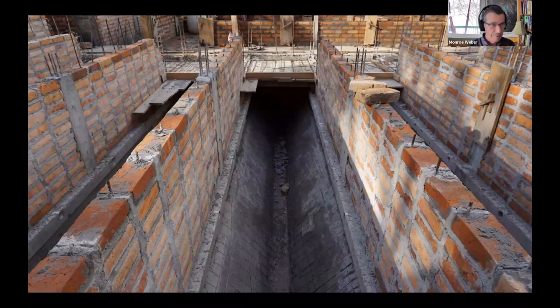And the reason is that these are load-bearing walls that have to be waterproof and have to resist significant hydrostatic pressure, because you have to be able to drain one tank while the others are still online. And that means there's the full water pressure pushing on these walls in either direction, depending on which side you drain. And so to accommodate that, there's rebar, and you can see the rebars here. There's rebar that goes right down through between the bricks. So in the mortar, in both directions, both horizontally and vertically, there are rebars embedded, and that's what makes this a reinforced masonry wall.